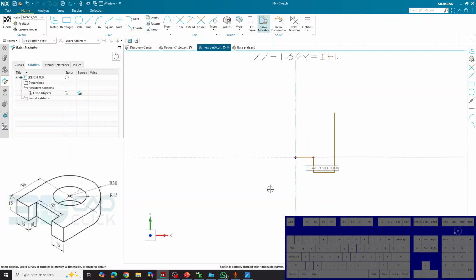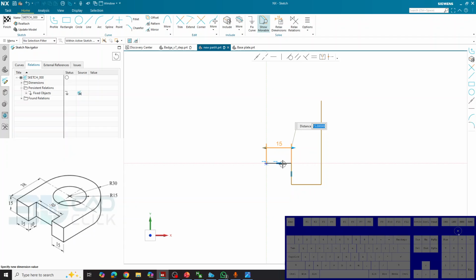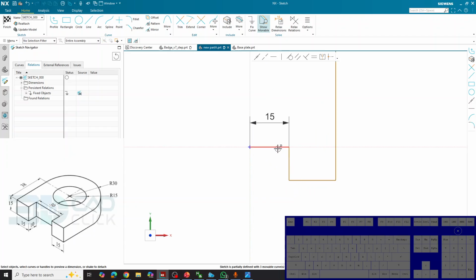The length of this line, because we're splitting it in half, instead of being 30 as it shows on the sketch, is going to be 15. So 15 over here. Press yes. As for the distance between this line and this line, the left side of the sketch says it's 10, so we'll use that because it's the same for both sides.